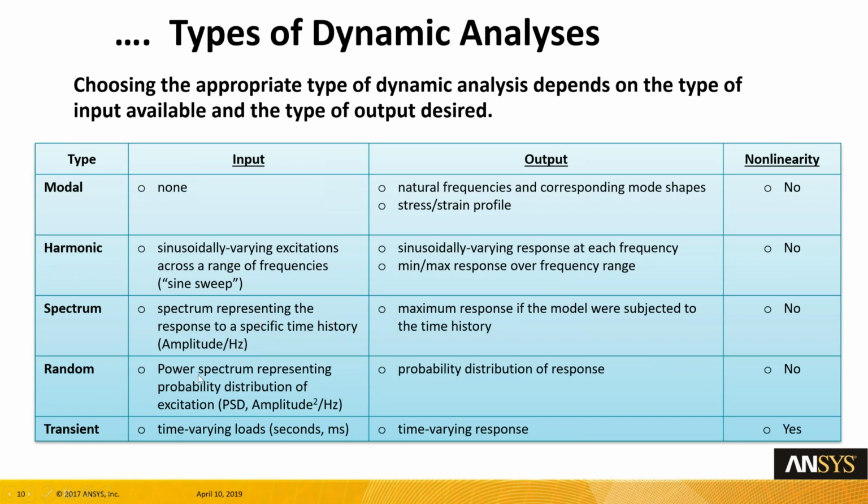Spectrum and random vibration simulations. In a spectrum analysis, you would input a spectrum, an earthquake spectrum, for example. That would be the input. And then as an output, you get the maximum response of the model when it's subject to this time history. And again, there's no nonlinearity.